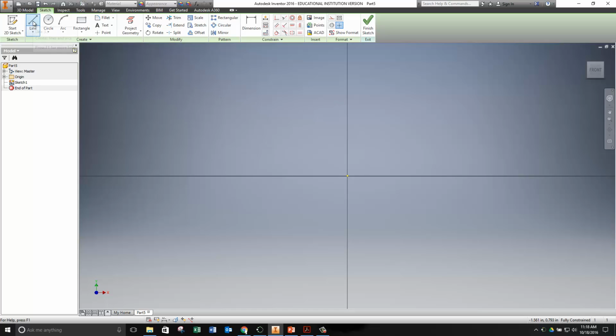Using straight lines, I'm going to click to start drawing the shape. And I'm going to draw the bottom edge. Don't really worry about the dimensions right now. Just get the shape approximately correct. I am pausing and letting the computer snap to horizontal, snap to perpendicular, snap to vertical, because that'll help me keep the shape cleaned up. Notice right here it'll line up with the end point of that bottom line. That'll help me get those two lined up.